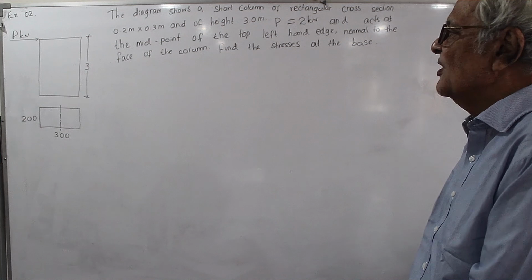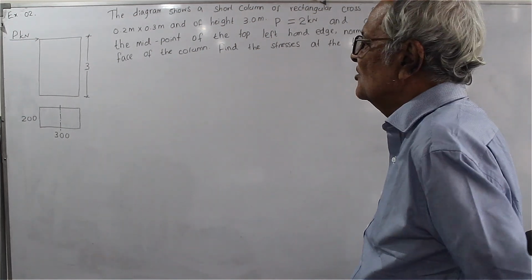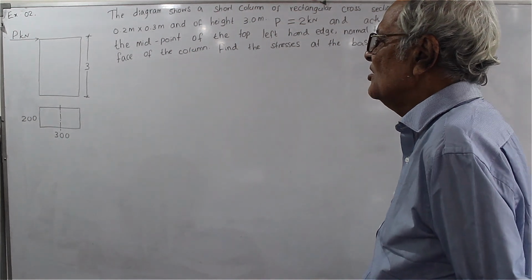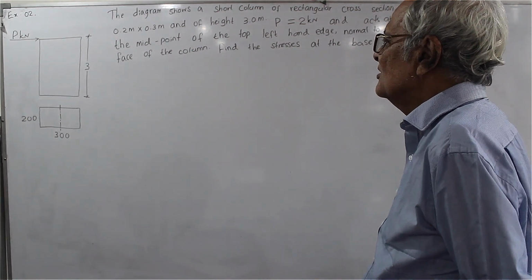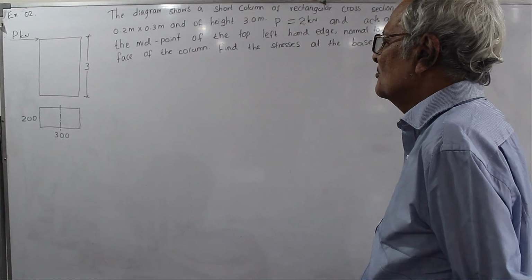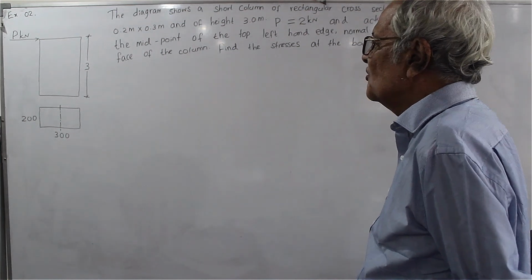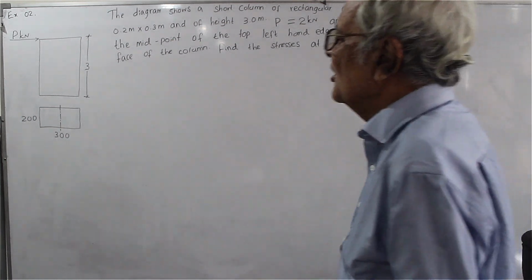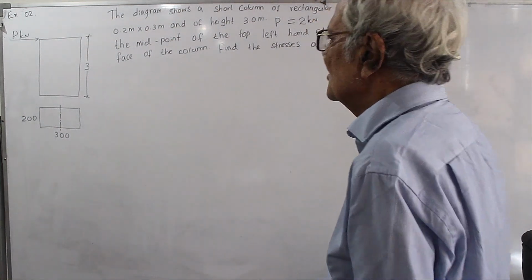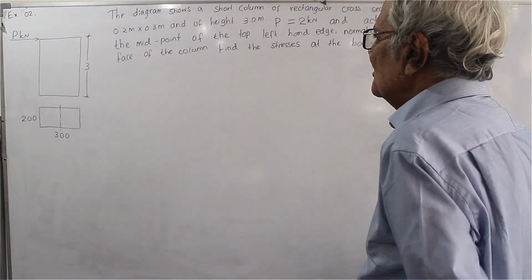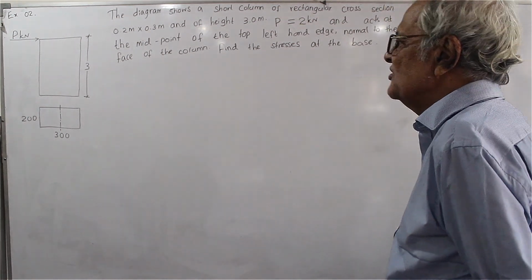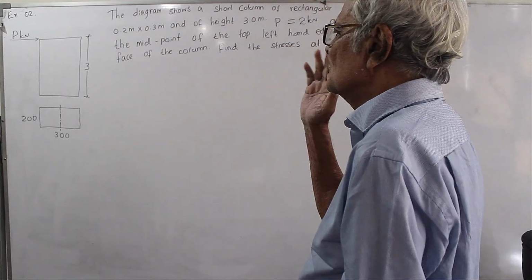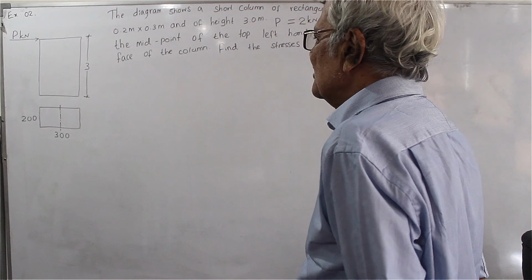Now in this problem there is no external vertical load applied, and therefore under the force P, the column will rotate clockwise and break down. Therefore we have to consider the weight of the column as the vertical load. The weight of the column is that which resists the rotation of the column under force P.